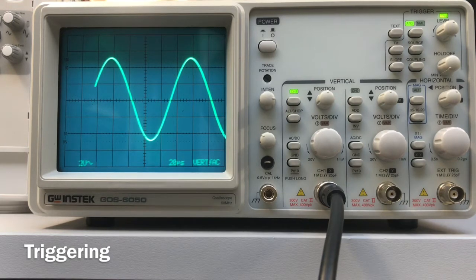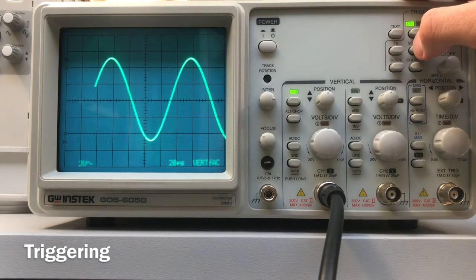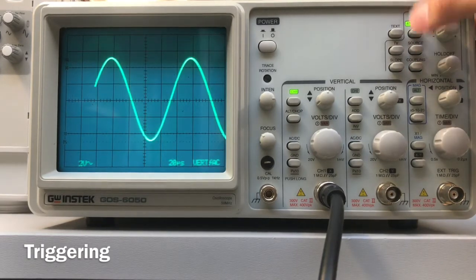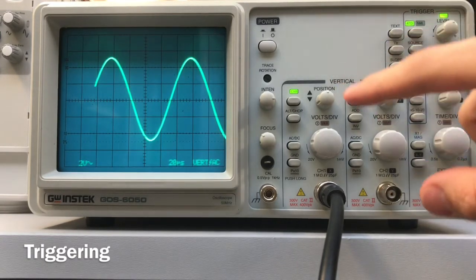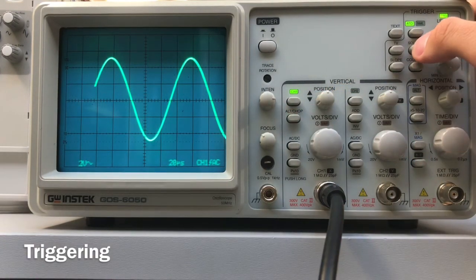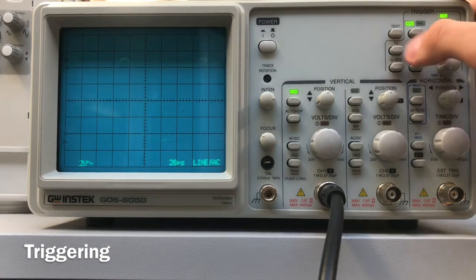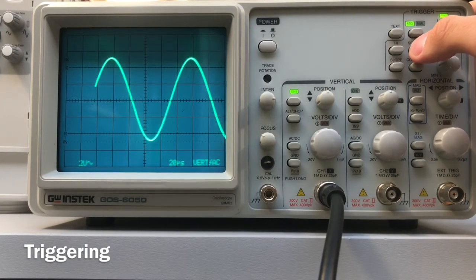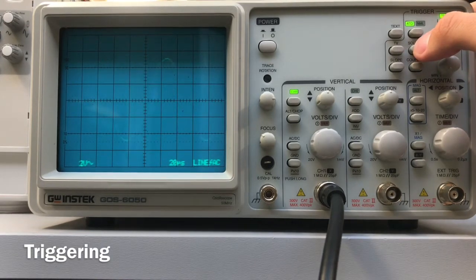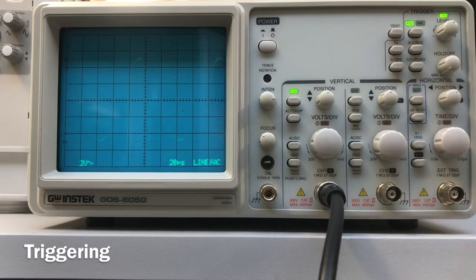Now you can use different triggering buttons to trigger the source. So by changing the source, you can choose which source you're using. Vertical just chooses the one you're using, so channel 1 in this case. Then you've got channel 1 and channel 2 here, and then the other two options you have are basically line, which compares it with the AC power source.